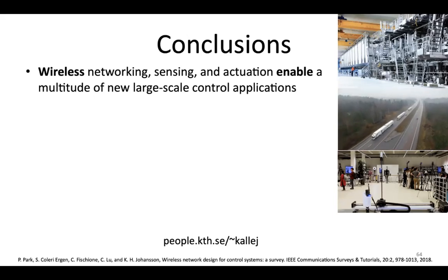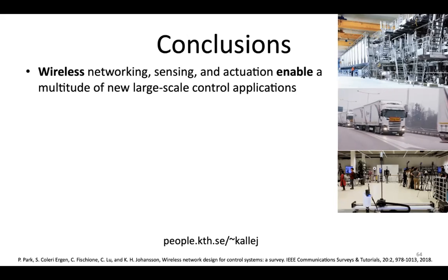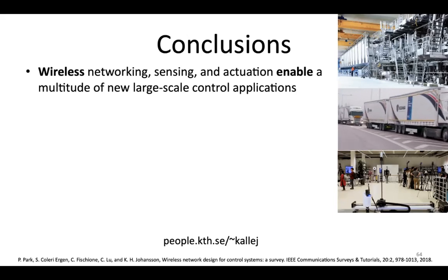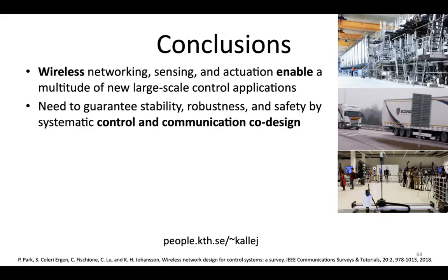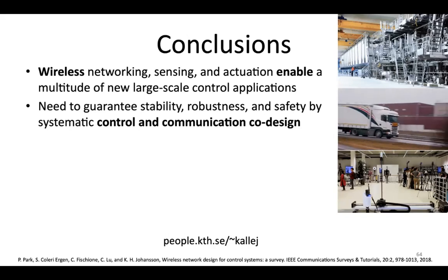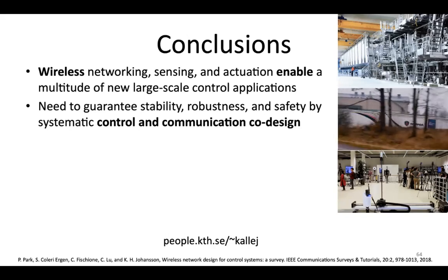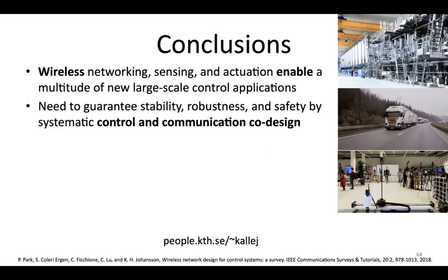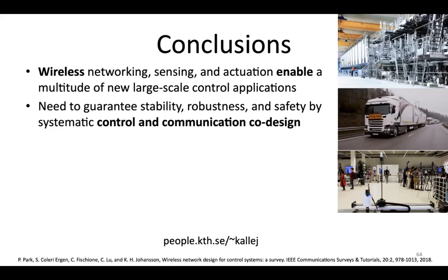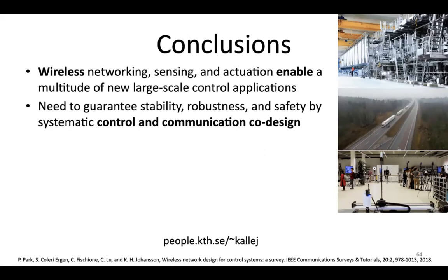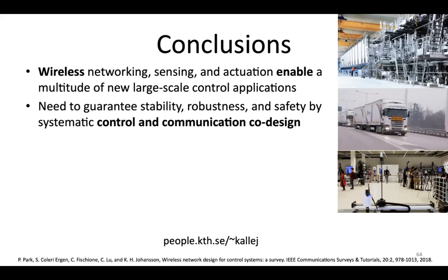I showed here also something we are doing with platoon control using very similar techniques. It's important to be able to guarantee the stability, robustness, and safety that are required for this control application. So there needs to be a systematic way of doing this co-design.